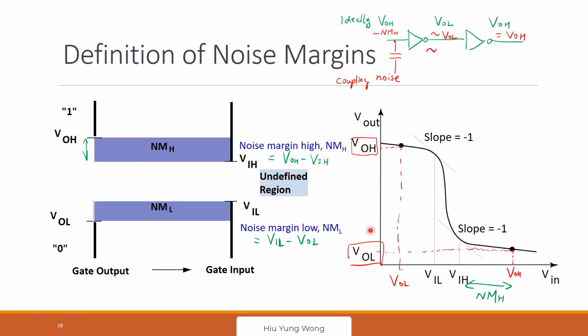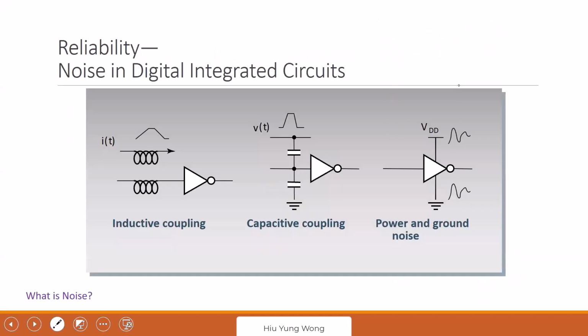Okay. But this just guarantees this steady state won't fail. There are many other things that can make your circuit fail, which have the frequency component. Of course, the coupling strength is related to frequency. For example, you can have inductive coupling, capacitive coupling, right? You have two wires running over. You have a capacitance. You can couple the signal to there.